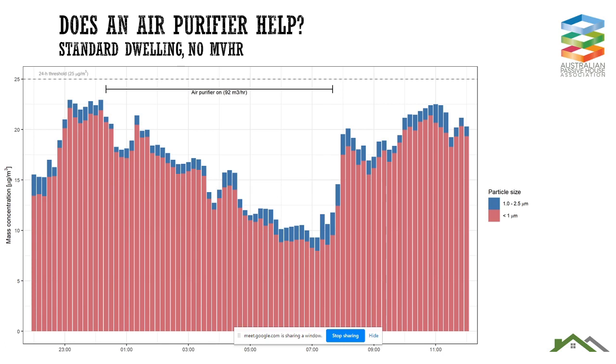And I imagine the other argument we could make from a passive house point of view is that the level of infiltration across the building envelope is so markedly reduced that arguably we might be able to size for a smaller purifier, but conversely, you are maintaining a constant level of infiltration across the mechanical ventilation system, which is likely to be your weak point.